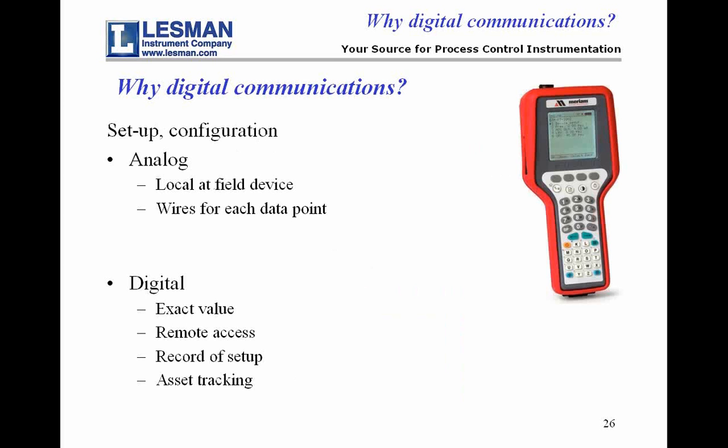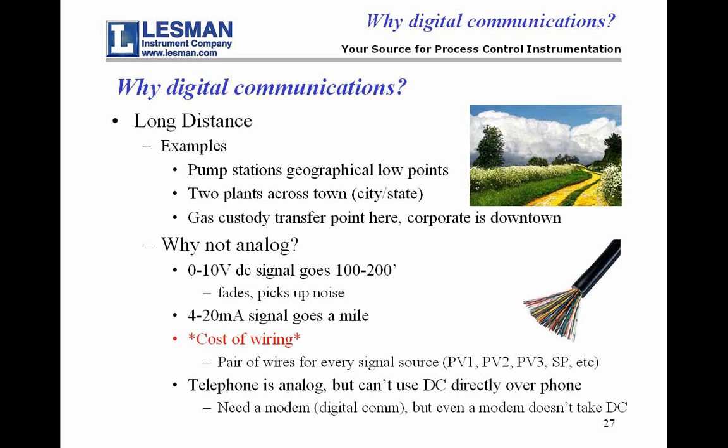HART has been around for at least 20 years now, and HART gives us the ability to set up or configure field instruments out there. And with recent advances in HART, it also gives us the ability to record those settings changes and configuration changes so that we can track assets. If you compare this to the strictly analog world, you're stuck with pots and bench settings and all that kind of stuff. It's a one-time thing and a lot of handwork in order to record the settings and the setup that's been done on it.